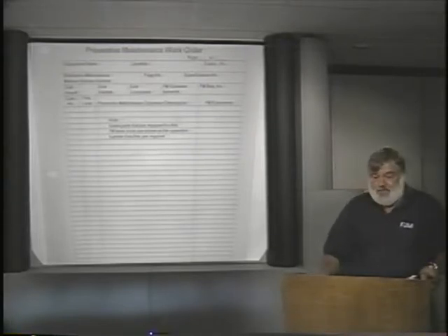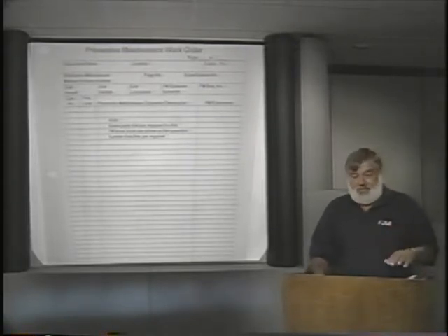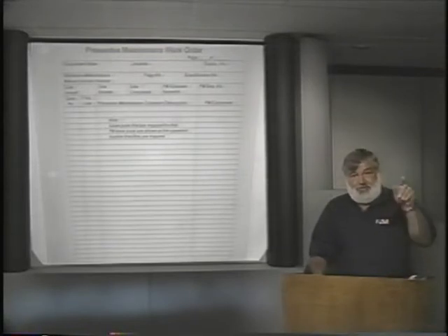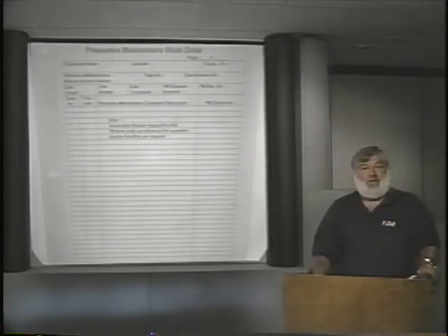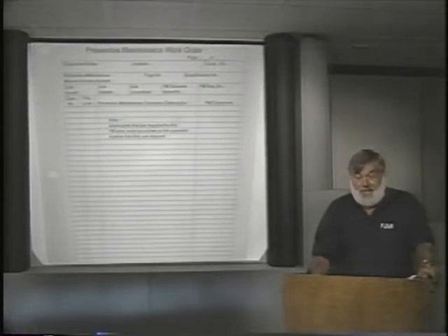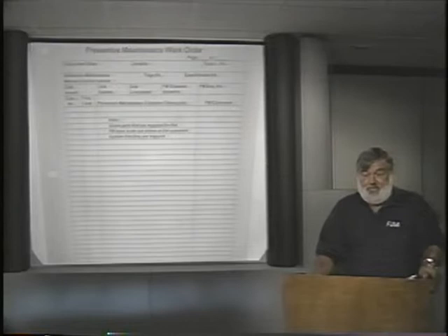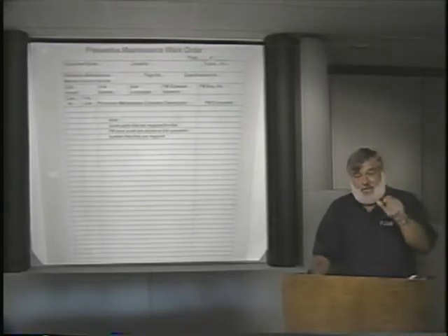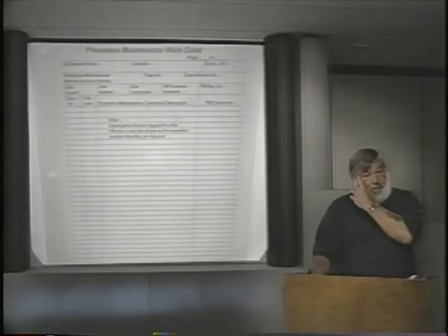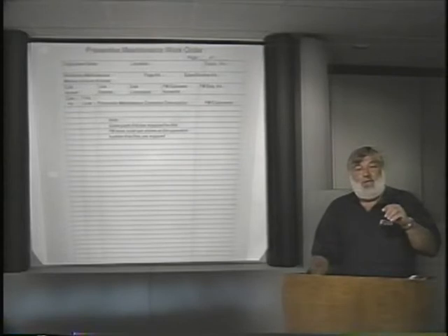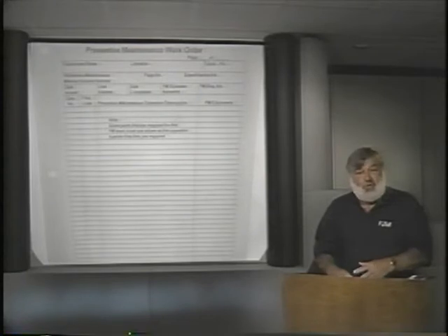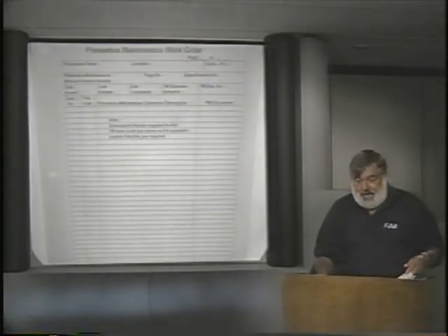If this document was going to be used to deliver material to the job site, then you notice in the heading of this particular PM4 form, we have not only the equipment name, but the equipment number on the left and the right-hand corners of the top of the document, but in the middle is the location. And that's extremely important when we want to have the storeroom deliver the PM document with all of the associated items to the job site.